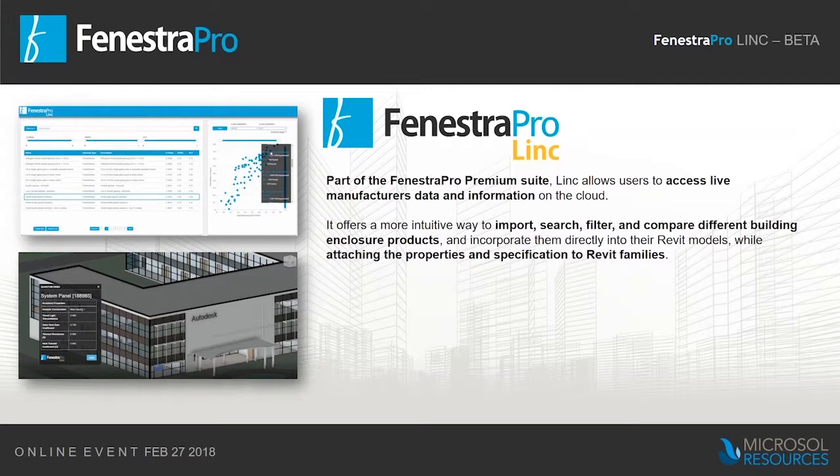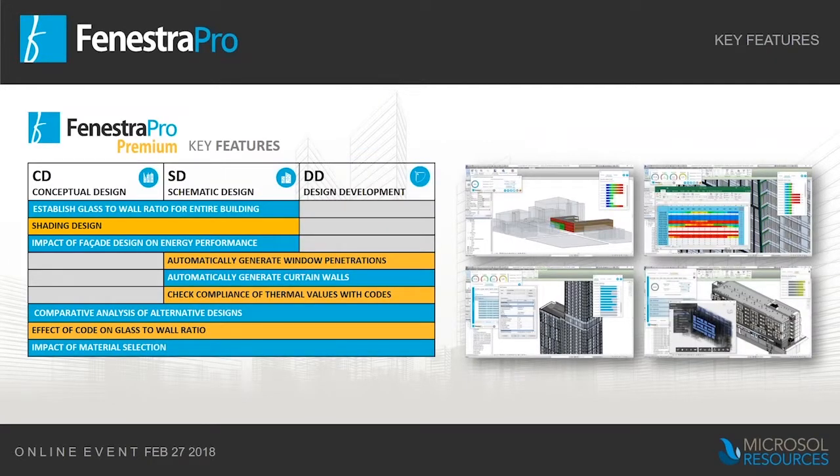For the moment, though, we'll focus on premium and looking at some of those key features across the different stages of the building design. So conceptual design, we can look at glass to wall ratio for the building. We can look at the impacts of facade design on the energy performance. And if I have 80% glass to the southern facade, what does that mean to the overall building? We can look at shading design, for example, and the effects of that.